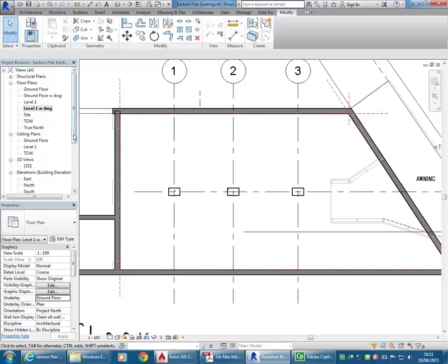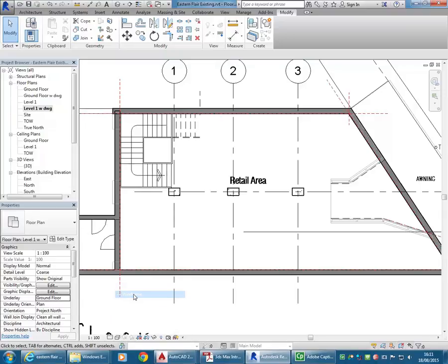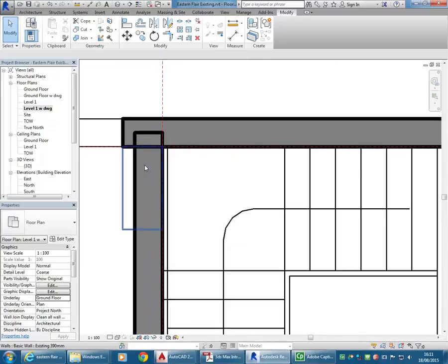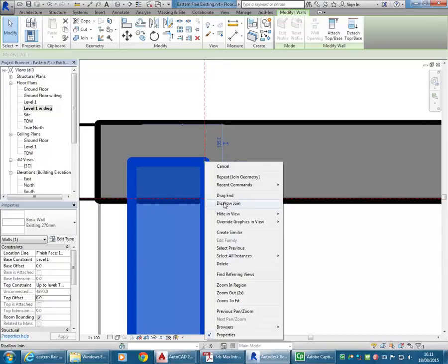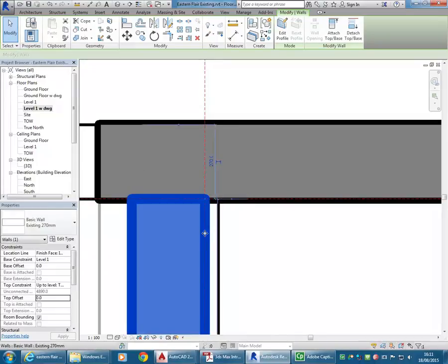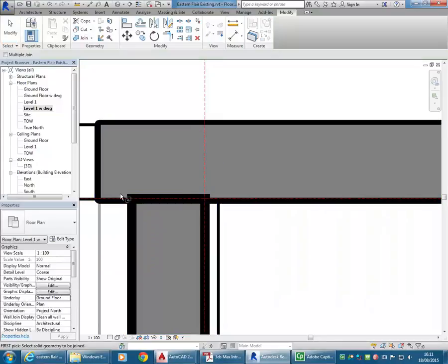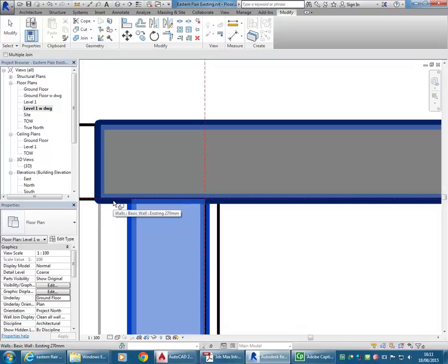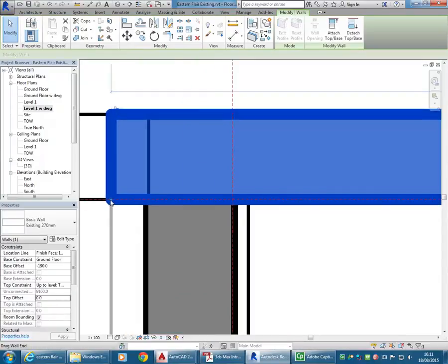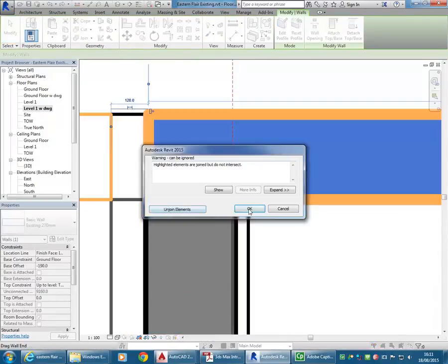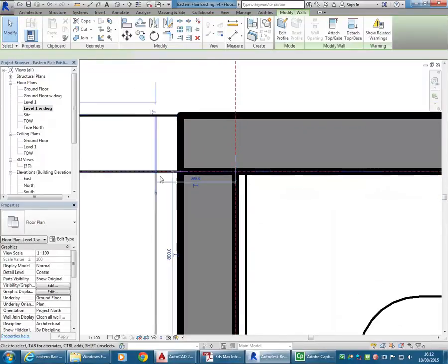So here in the level 1 view with drawing inserted, I can't see the Autocad drawing anymore because the floor is covering it, but I can now go to wireframe, and there you can see again we've got a little issue with the walls there, which I can fix again by making sure this wall is again set to disallow join. So I can then drag the end and manually use join. Well, actually here again, before I do that, this one I can drag back now and then drag the other one across.